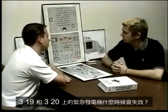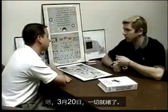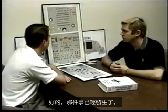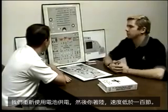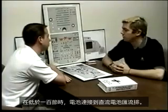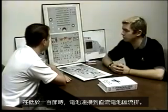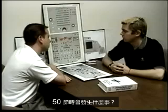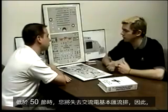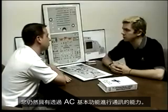When will you lose the emergency generator on the 319 and 320? Well, on 320, it's gear down. On a 319, it's when you get below 125 knots. Okay, that's occurred. We're back to battery power, and you land, and you get below 100 knots. Below 100 knots, the batteries connect to the DC battery bus. What occurs at 50 knots? Below 50 knots, you lose AC essential bus, and therefore you lose all the displays. You still have the ability to communicate through the AC essential.